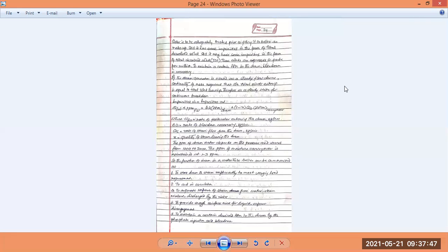So there should be a proper and sufficient way to separate them, so that the superheater doesn't receive any droplets of water. At the same time, the downcomer should not have any vapor bubbles, because they will reduce the density of the downcoming water itself.